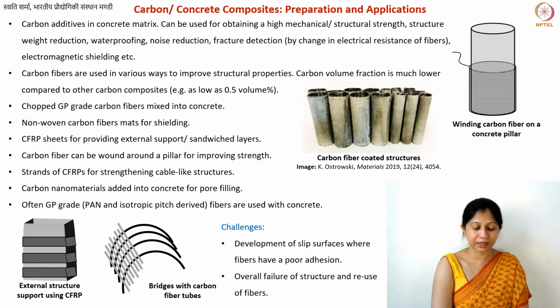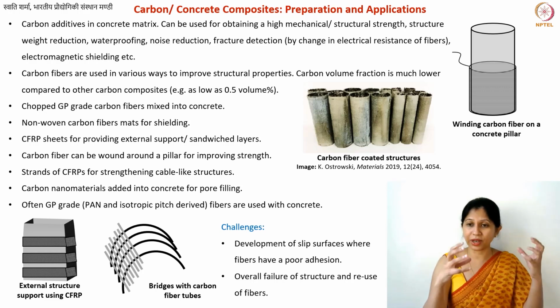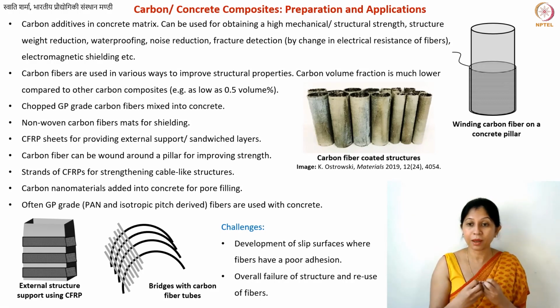This is something that you need to think about, because carbon fibers can be to some extent reused, but every time you reuse them, their properties or their value becomes very much lower, because you have brittle carbon fibers, so they may end up breaking a lot when you're trying to remove them from their parent structure and then trying to reuse them.